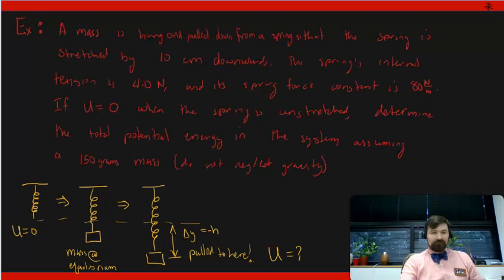So if I want to figure out my total potential energy, that should look like 1/2 of the spring times this delta y squared minus m times g times h, which again is delta y. Okay, so my potential energy for the system, if I go back here and look at what I've been given, this right here is delta y.